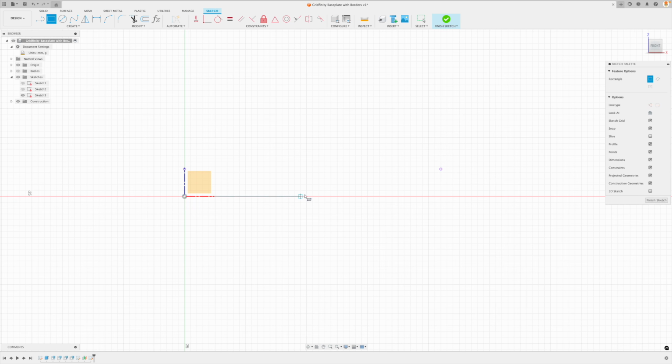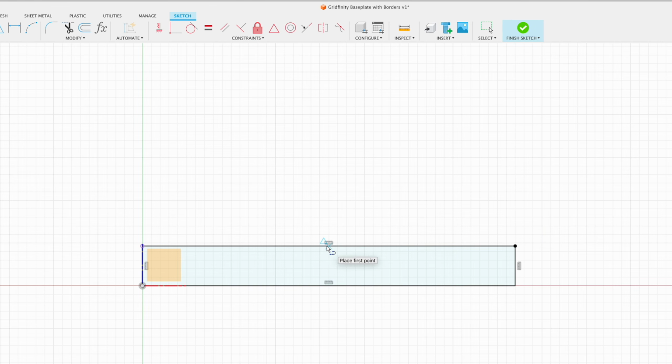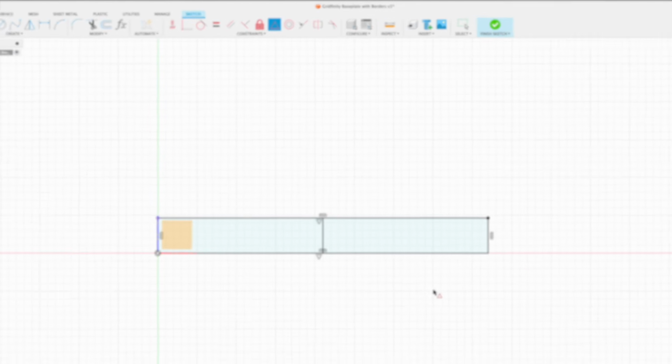I'm going to create a 2-point square and grab the origin and then grab this top point right there. Next, I want to put a reference line down the center right here, and this is going to be our center line. Now, just to show you a little tip, I could search with my mouse and try and find that triangle, which is the center point, or I can just create a line off into space over here and then click the midpoint constraint, endpoint to line, and that automatically locks it. Endpoint to line. So that locks it in.